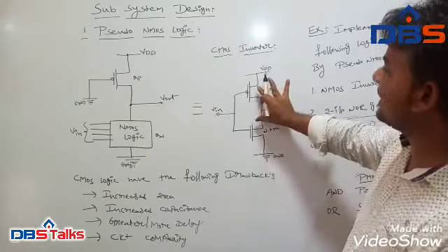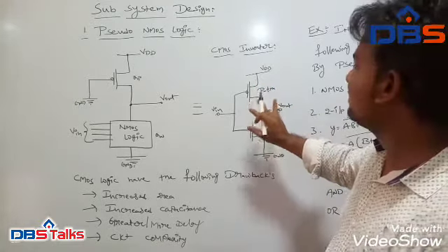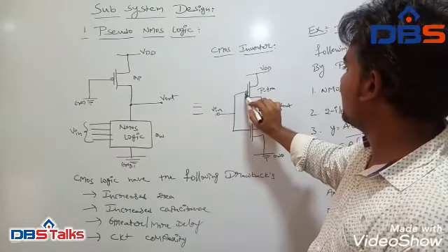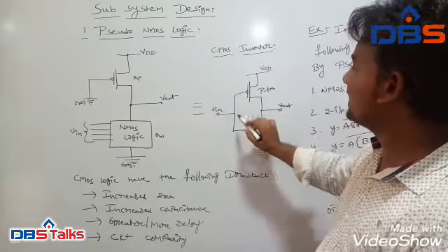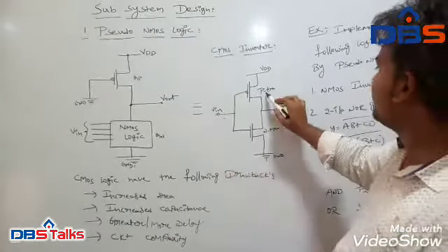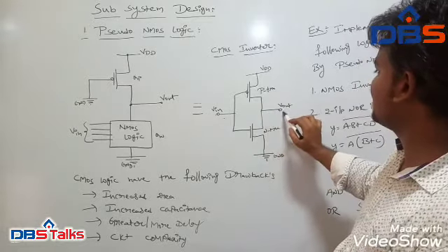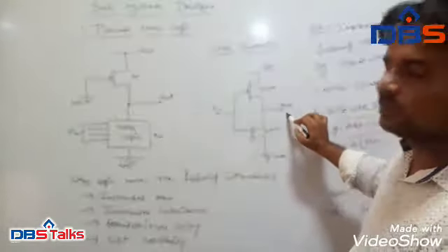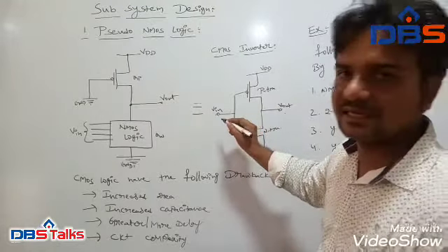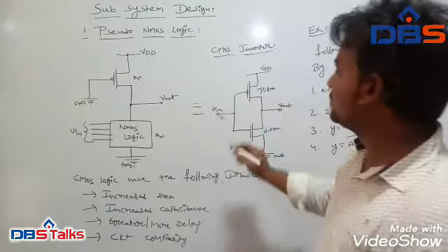Whenever we connect two transistors together, they act as an inverter. At the gate terminals of both transistors, we apply Vin voltage, and between the source and the drain terminal of the N-type transistor, we take the output of the design. Coming to the operation, consider applying 0 to Vin.